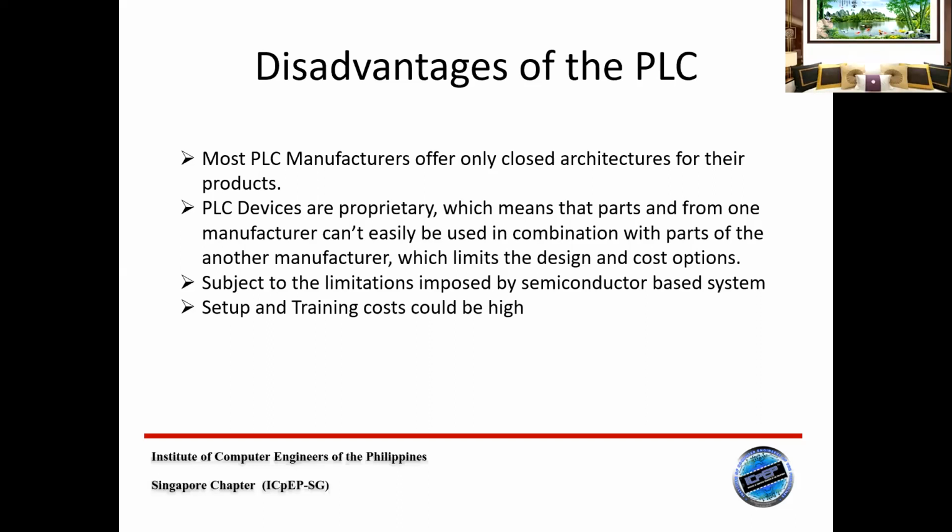It is not easy to change the brand of the PLC. If you have a machine that is using Keyence and you want to switch it to Omron, it's very difficult because you will have to reprogram all the programs in your Keyence brand. So it's very difficult to change the brand.